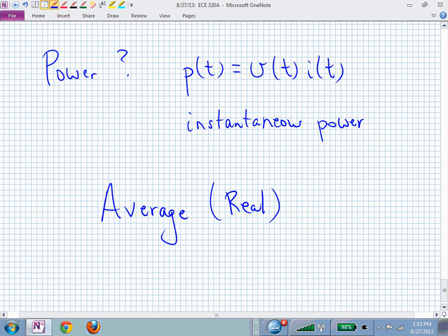the real power. And we'll keep these different powers separated by the units that we assign to those. And this is what you will see from the power company. You'll get a bill and it may actually show you the energy consumed. It'll be watt hours or kilowatt hours. But there's a watt in there, isn't there? It's just multiplied by a time to give you the energy. But you could then divide out that time and get your average power over a 1 month period, for example.